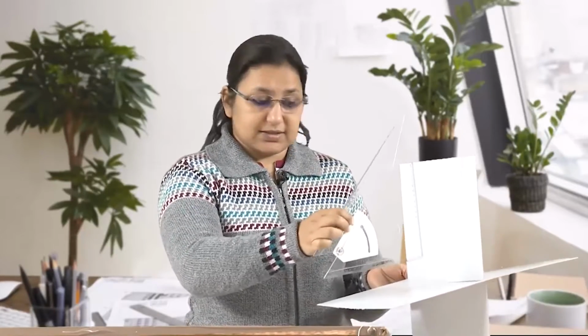Now, just imagine that we have, say, a triangular plane which is perpendicular to both the reference planes, the horizontal plane and the vertical plane. A plane which is perpendicular to both the planes will be something like this, perpendicular to both the HP and VP. So, this plane which is perpendicular to both the planes is going to be parallel to a side projection plane,